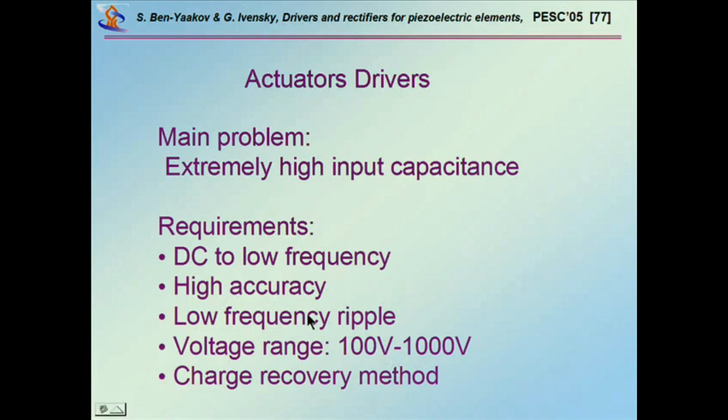Actuators have extremely high input capacitance, really very high. We are talking about a few microfarad. I can tell you that I've been working lately on an actuator that is used for an optoelectronics device. It has 6 microfarad capacitance.